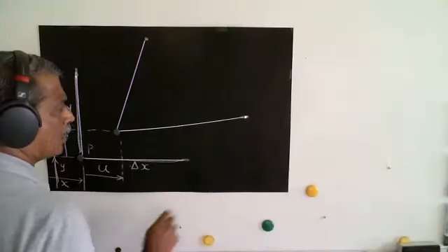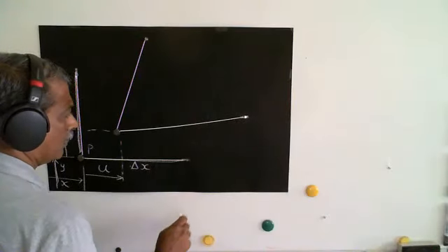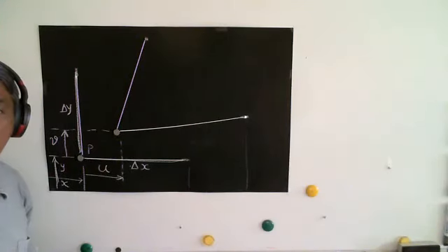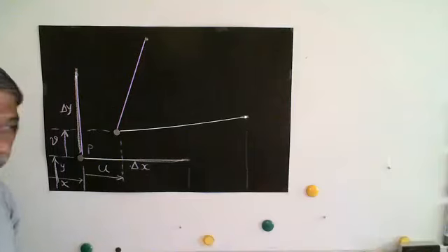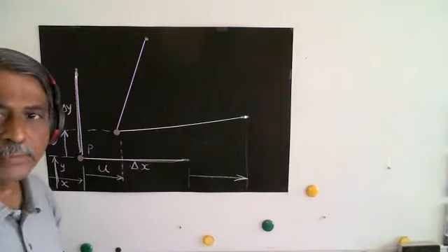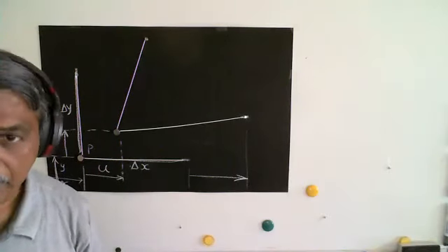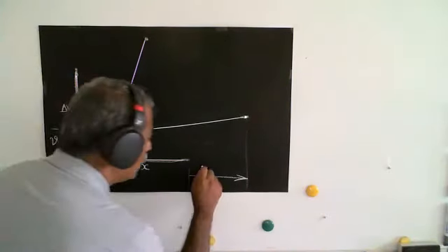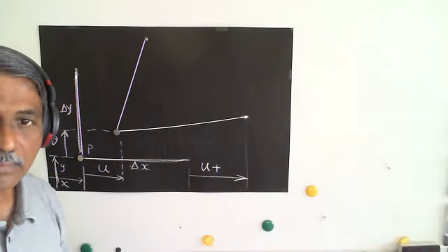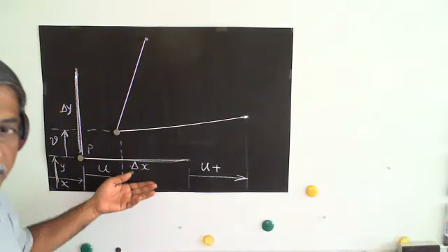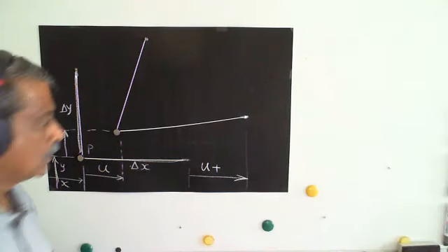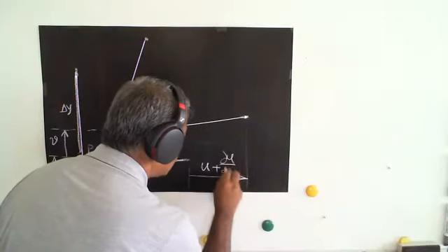So it has elongated now and it has also displaced. So definitely between this and this is not u. It has to be something else. What would that something else be? Let's use the continuity principle, like what we did there. It should be u plus the changes that have occurred in the displacement, dou u by dou x times delta x.